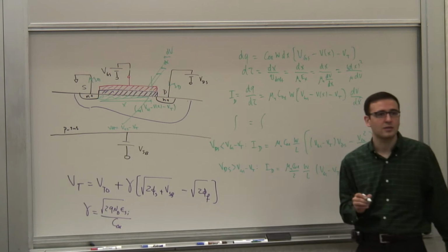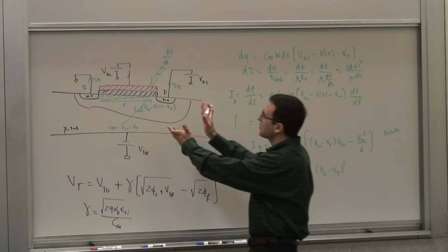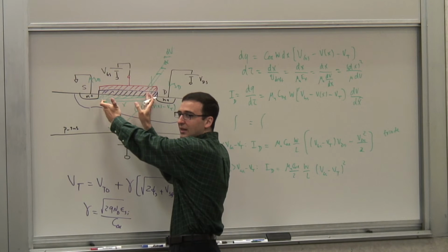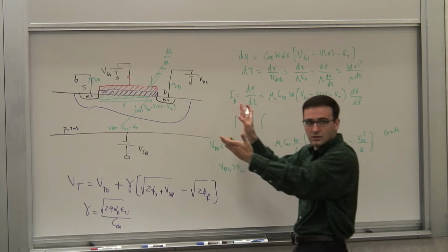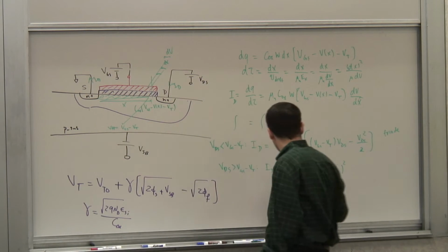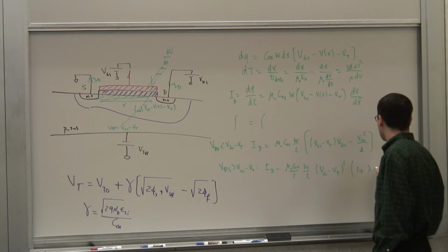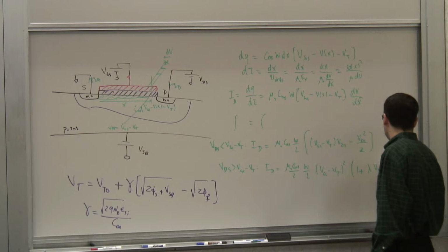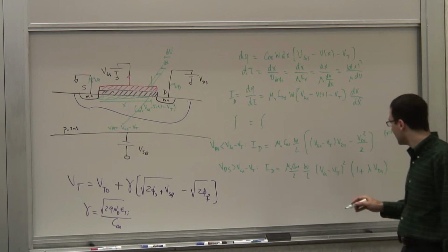But we know there's still this secondary effect, which is basically the modulation of the channel length, the effective channel. So we saw the channel length was modulated when you change VDS. So it was not large, but there was that term. So we captured that as a second correction term, which was 1 plus lambda VDS, to account for the variations in that direction.